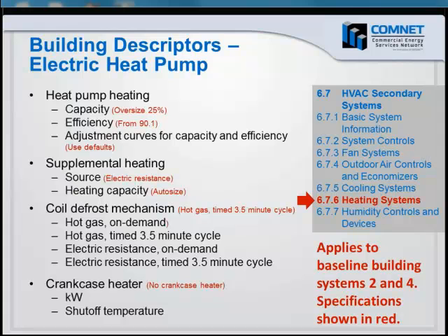The next question about heat pumps as well is, this has been a question interpretation that's come to the 90.1 committee. At 40 degrees, we're specifying that the supplemental heat is activated, but it's not clear that you're still using the refrigeration cycle for heat as well, and what's the lower limit of that? Oh, yeah, it's a good point. I've always assumed that basically they're integrated, so that the compressor keeps running and the supplemental heat comes on as needed to meet the load. But have you guys got an indication that there's systems where the compressor literally shuts down at say 40 degrees and you run entirely as an electric resistance heater?